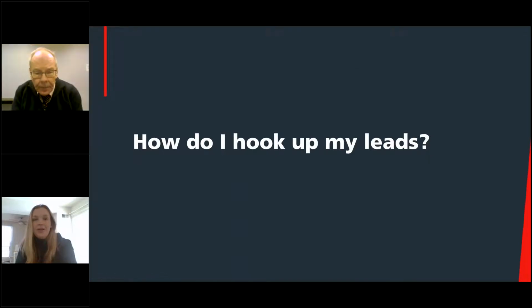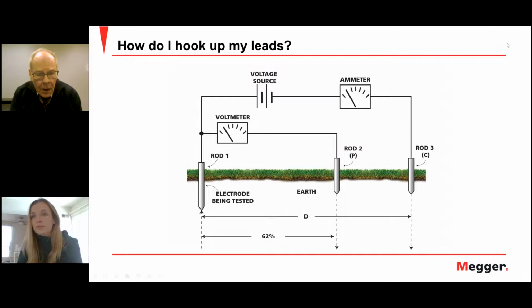Okay. And how do I hook up my leads? Okay. On this one, this is pretty much according to the procedure that you're going to be following. So what very often is done, I mentioned this before, the operator hooks up the leads, runs them out the maximum distance and takes a reading. And yeah, if you're lucky, you may get a good reading, but you really don't want to do that. You want to hook up your leads and follow a test procedure.